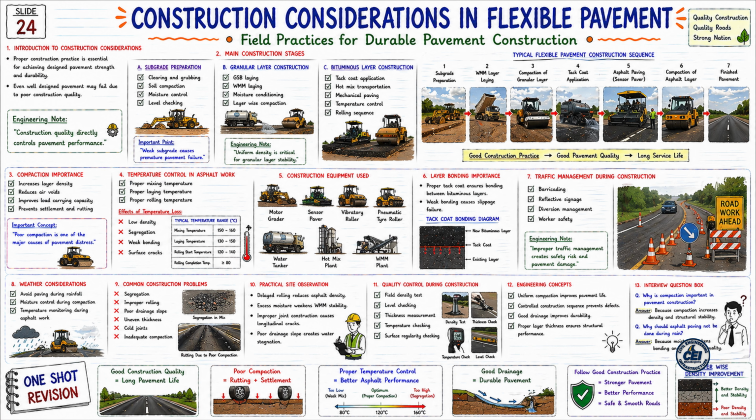Weather considerations. Avoid paving during rainfall. Moisture control during compaction. Temperature monitoring during asphalt work. And asphalt paving should be avoided in rainy conditions. Now let us look at the 9th topic.